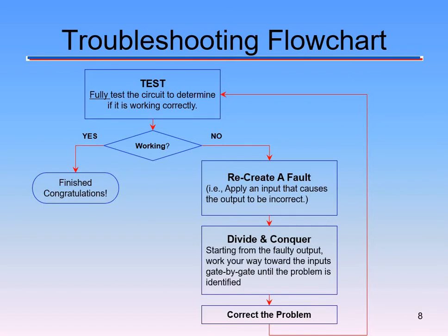Recreate the fault. In what cases is your circuit not working? So when we start toggling through inputs, and we go 0, 0, 0, 0, 0, 1, 1, 0, 0, or we go all the way up to 1, 1, 1, or things like that. Which specific case is it faulting out at, 0, 1, 1? Is it faulting out at 1, 0, 1? Are some of your readings correct and some of them not? So recreate that fault, all right, and then we can use a probe to go through it. We can use the multimeter, and we can see what's miswired in that step.